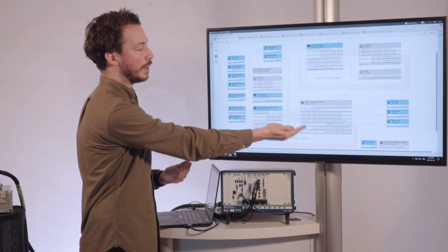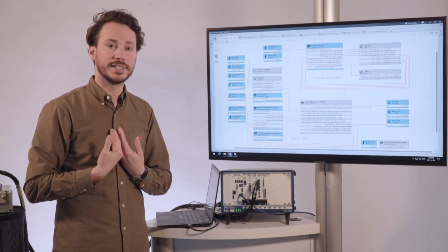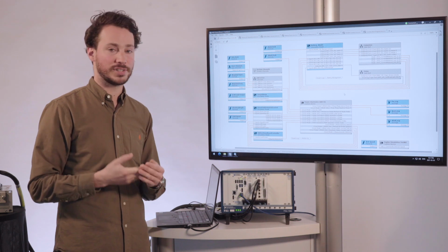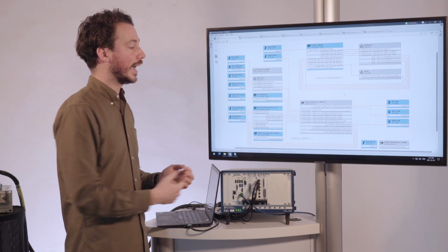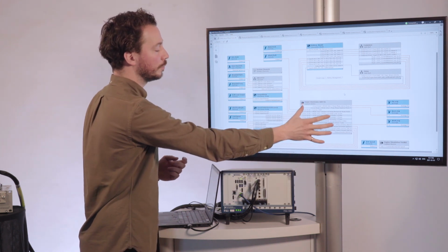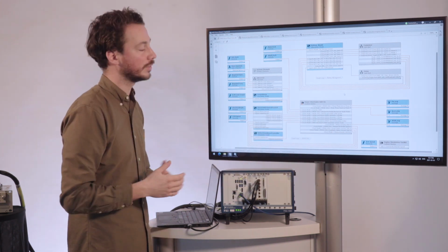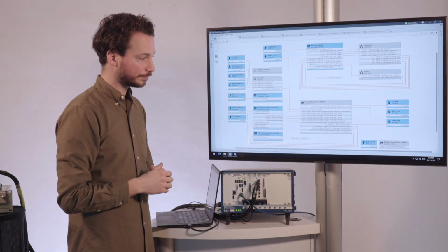This is connected to the power electronics add-on. The power electronics add-on is what we talked about before from OPAL-RT. It is the custom device meant to simulate the power electronics of the vehicle as well as the machine. And this is one closed loop, as we can see right here, between the plant model being the inverter and the traction drive with the field-oriented control.